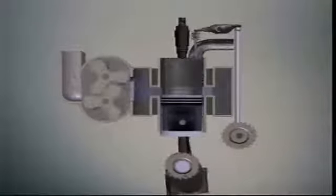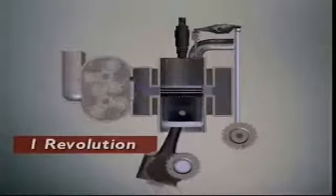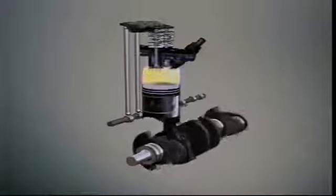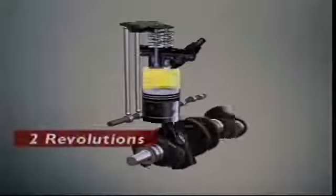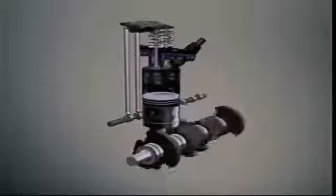In one two-stroke engine cycle, the crankshaft makes one revolution. How does this compare with a four-stroke engine cycle? How many revolutions does its crankshaft complete from intake through compression, ignition and power to exhaust? It makes 2 revolutions. In that time, what happens to the valves?